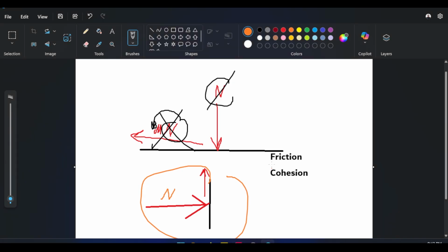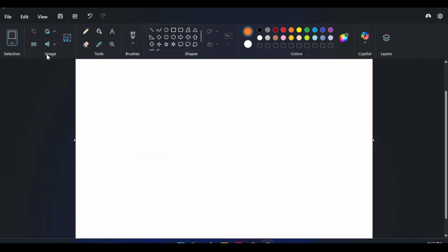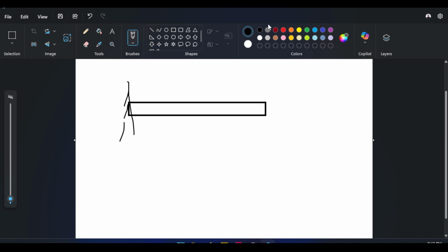Well, from the name, it's basically a gap, meaning if I have an element like a beam like this, and it's fixed on one side, and it's being pushed by a force up, if I add a gap, let's say the gap here exists. Gap means that the reaction will only activate once the beam touches that gap. As long as the beam doesn't touch the gap, nothing will happen. This is one of the hard contact problems, by the way, because there are two conditions. Condition one, where the reaction is inactive because the beam is not touching the gap.